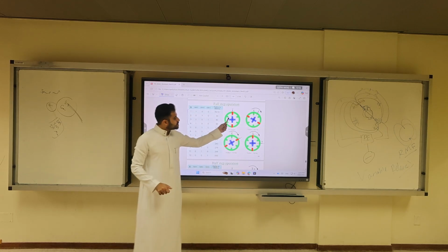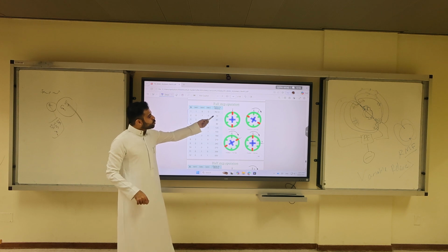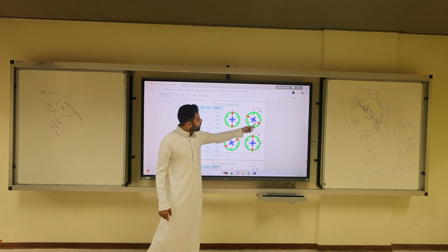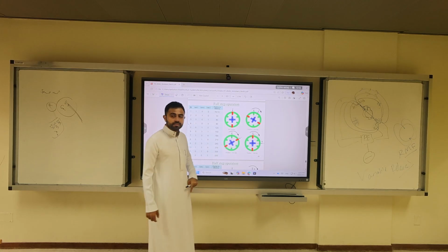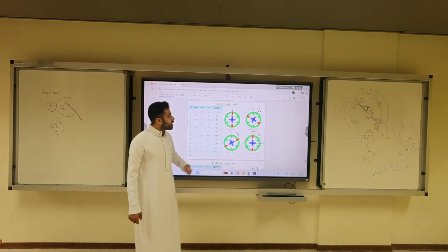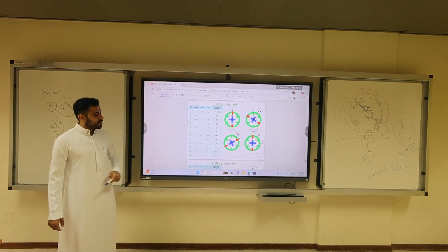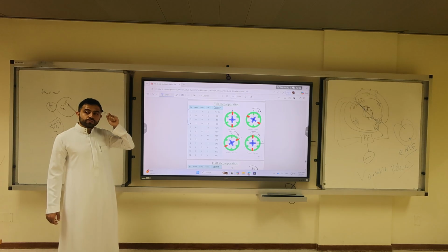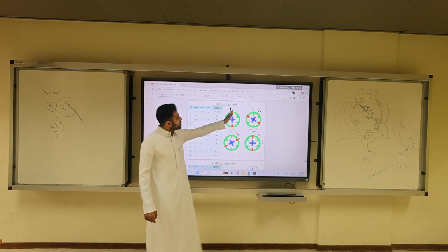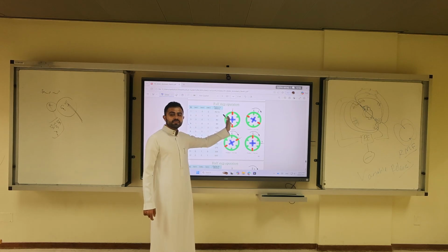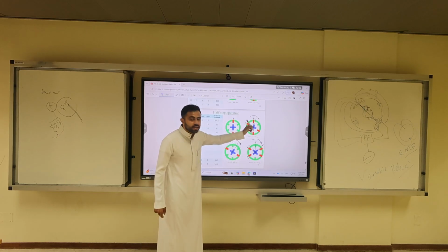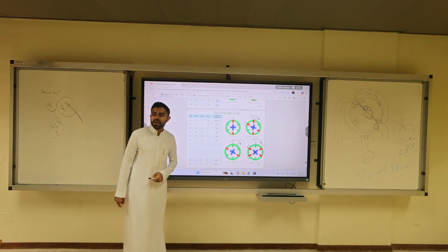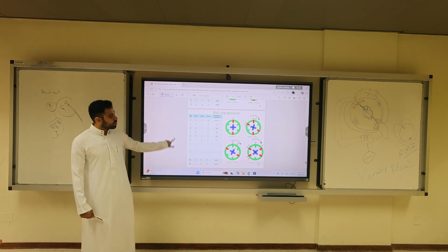Now you moved how many degrees? 30 degrees. How to move another 30 degrees? Make coil 3 active. And then the B will be here, the A will be here. So A will rotate. And then you change the pulses. Okay, what if I want to move only 15 degrees? What will happen if I keep 1 energized and energize 2 at the same time? The angle will be similar to the half rotation, and it will be only 15 degrees. This is how a stepper motor would work.